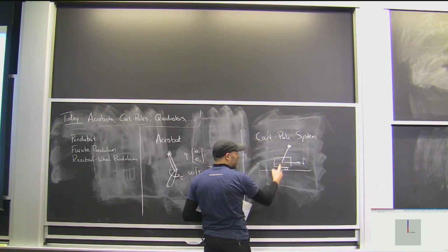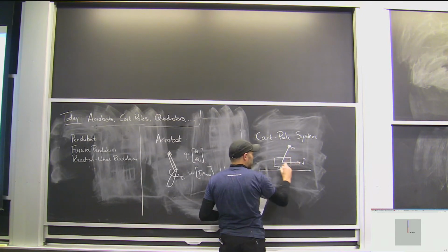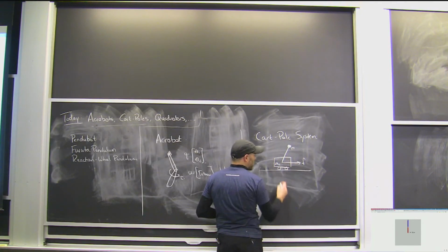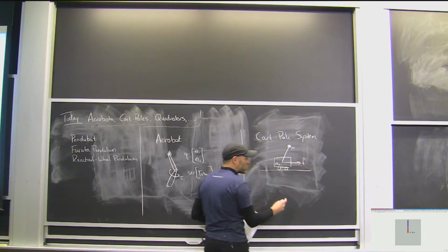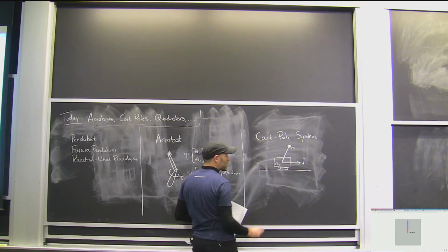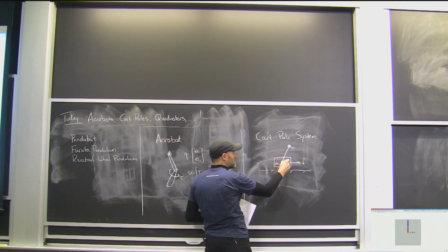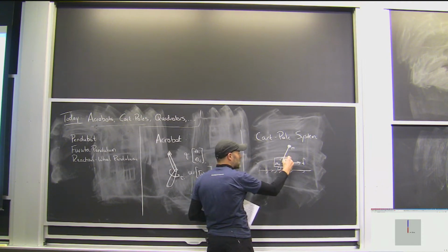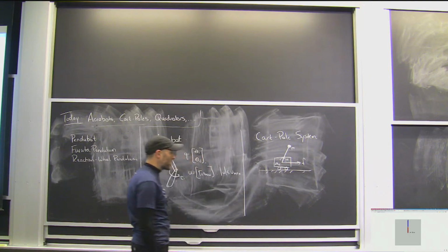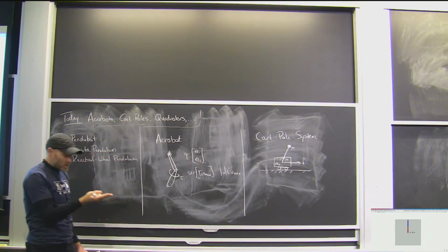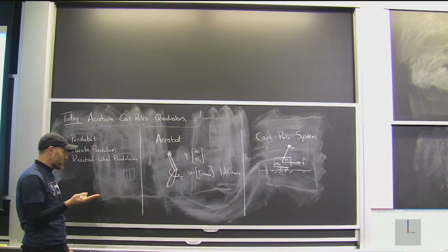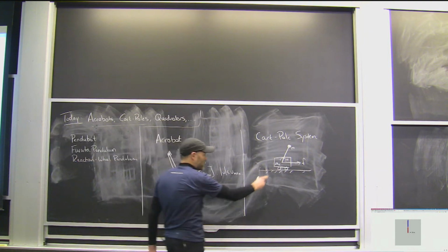This one is the simple pendulum with a mass over here and a mass on the cart. The control action is just to apply a force on the cart, and there's no actuator at the pin joint. This is theta, but there's no actuator there. So it's kind of like a simple pendulum attached to a double integrator mass on wheels.